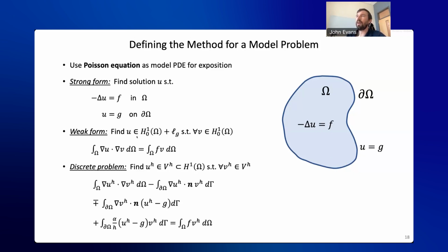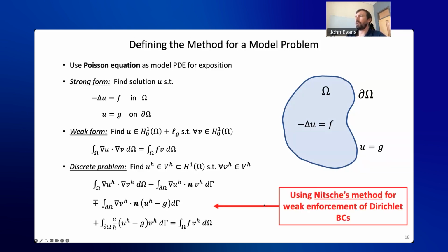And here we just basically took this PDE, multiplied by a weighting function, and integrated by parts. And the discrete problem that we utilize for immersed analysis much of the time looks as follows, if we use so-called Nitsche's method for weak enforcement of Dirichlet boundary conditions.